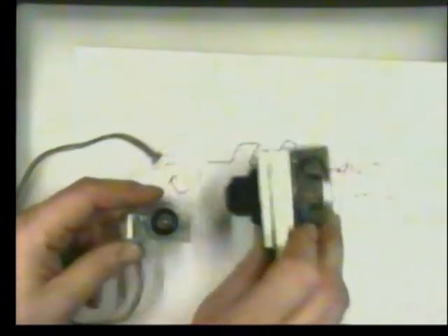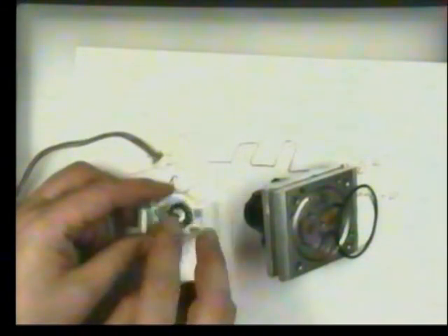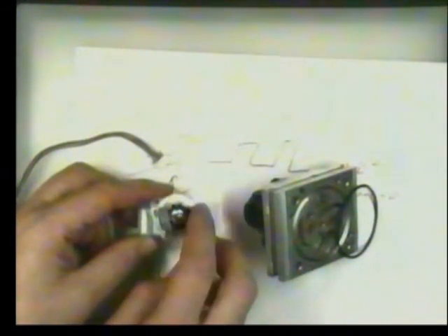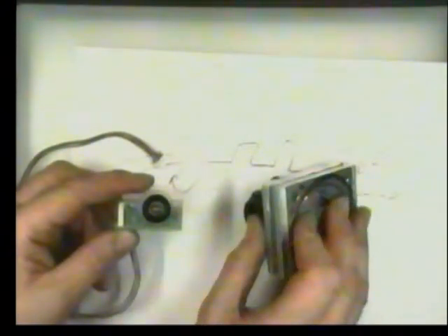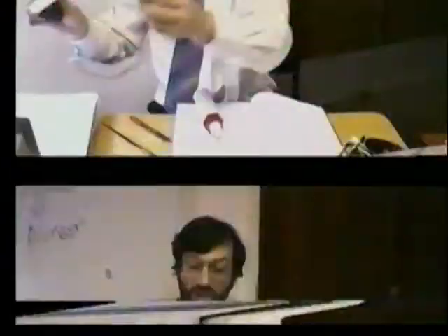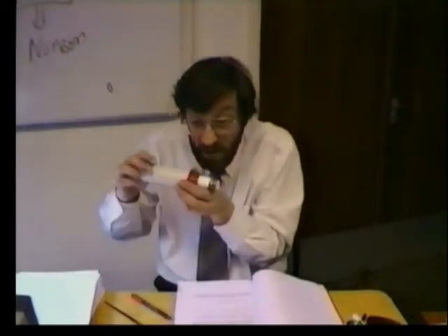We know in our little turbine meter it can only rotate one way, so we just count the pulses in our program. Very, very easy to do. Water wouldn't back up down the pipe. But how can we cope with a rotating shaft, such as in a motor or a machine tool, that could reverse?